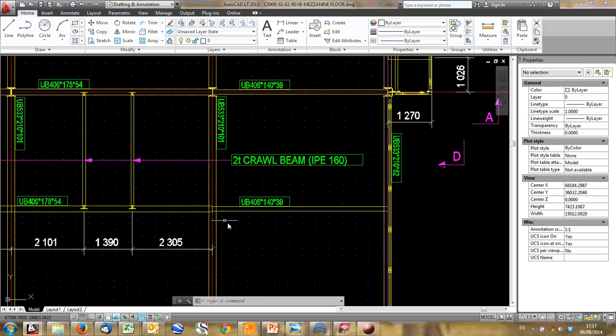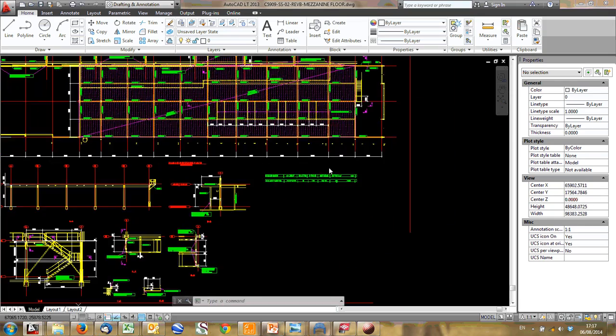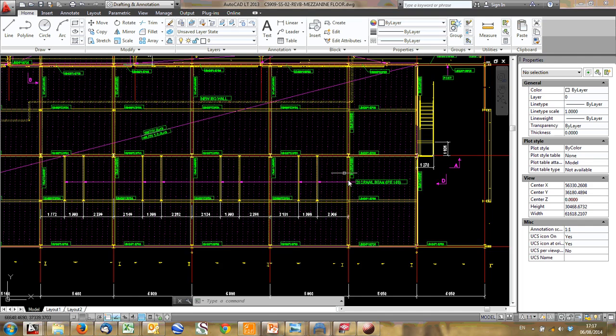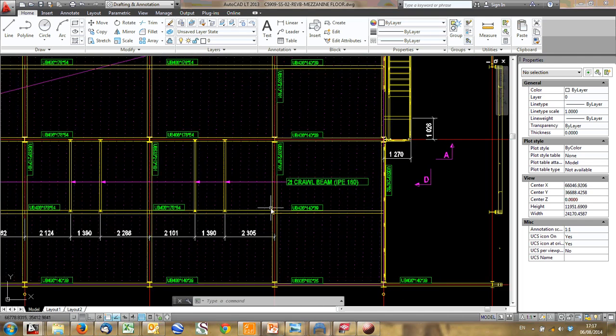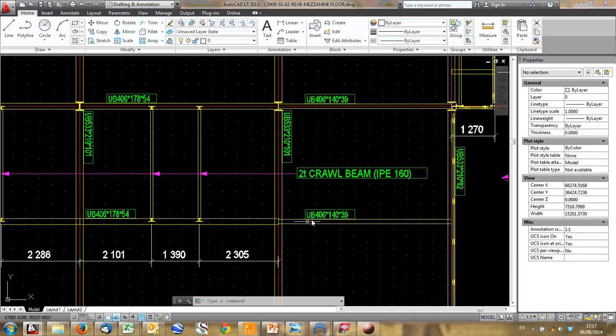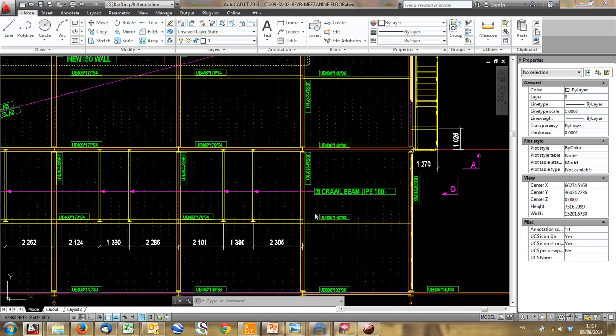These beams, as I said, are simply supported. You don't connect your flanges from one to another. You simply connect the webs together. You have a cleat or a thin plate or something, and you connect this beam to this beam. So you don't pass moment from this one here to this one here. You can actually isolate, so you know the force stays here and you know the force stays here.